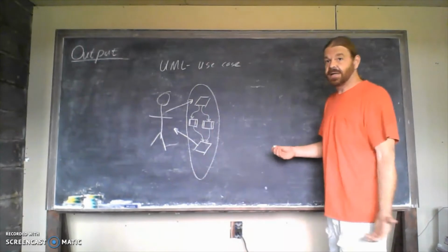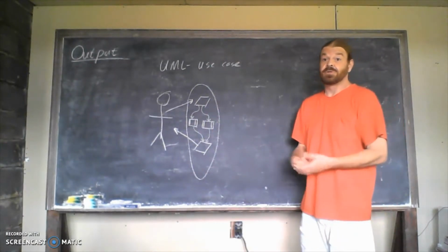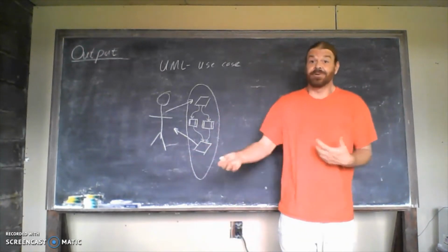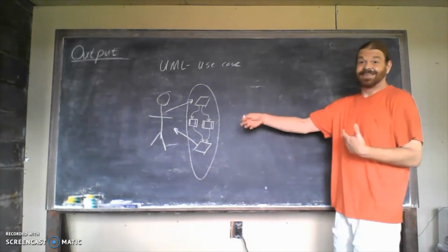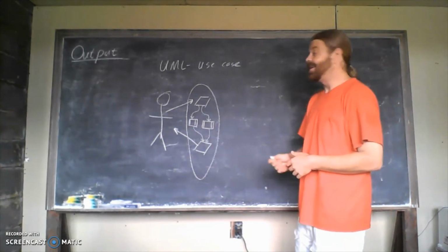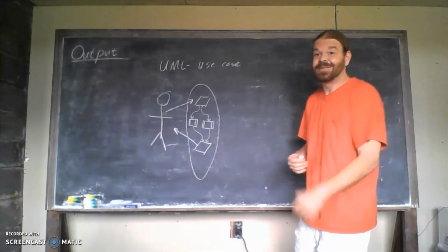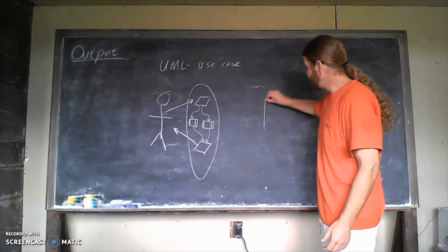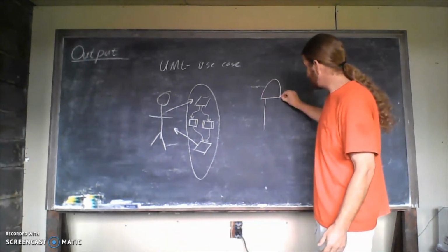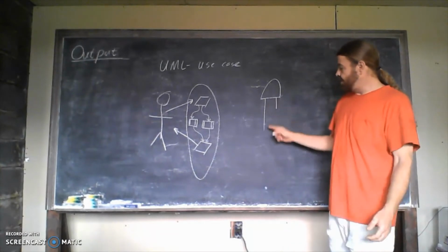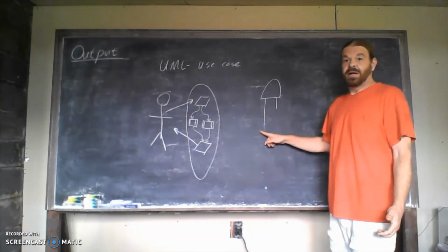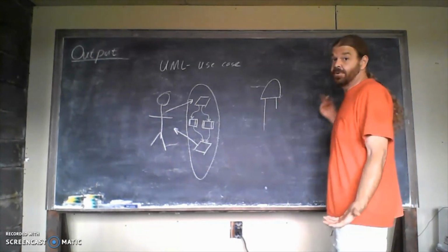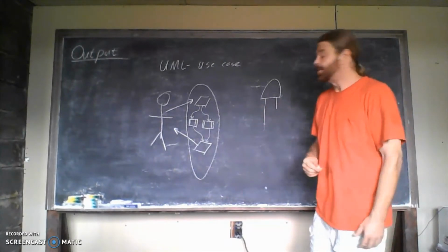We've seen some, right? Most of the stuff so far in these examples, trying to get the simplest case, we just need to see if the output is on or off. You know, if it's turning the next component on or not in a long chain of components, or is there something or is there not? So most of them so far, we were able to do with an LED. Simple starting point. Hook up some voltage, positive voltage coming into an anode, come back out the cathode to ground, and it comes on when we send the voltage.